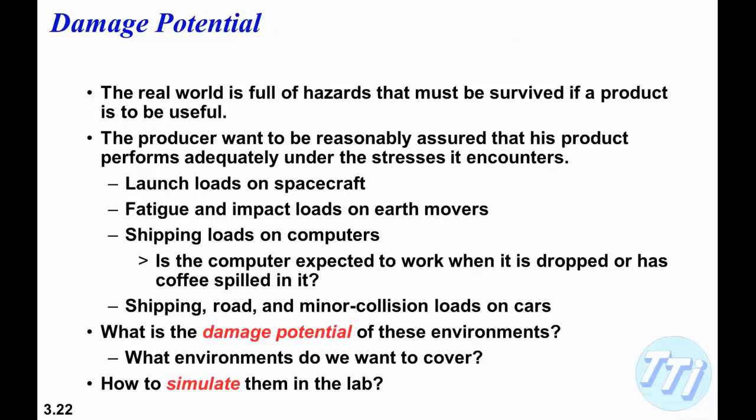So, the real world is full of hazards that need to be survived. The producer wants to be reasonably assured that his product performs adequately, and examples of that are launch loads, fatigue and impact loads, and shipping loads on computers. Is the computer expected to work when it's dropped or has coffee spilled on it? And the answer from our user standpoint is obviously yes. Does it need to survive shipping, road, and minor collision loads on cars? What's the damage potential of these environments, and how do we simulate them in the real world?